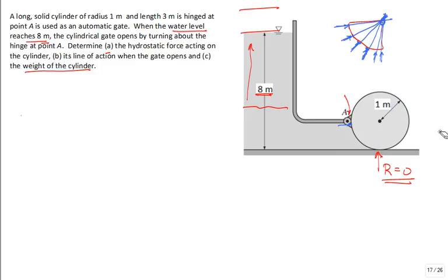All right. Now, if the water's pushing on this curved surface, then I can turn it around and use that curved surface to say that it pushes on a chunk of water that I'm going to cut out right here. So we cut out a chunk that looks like that. This is water. Let's do a free body diagram of that water. Don't forget the weight of the water, and that weight acts at the centroid of that funny shaped area. All right? Good.